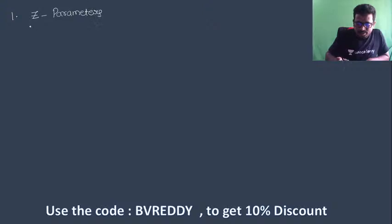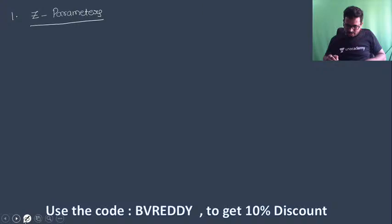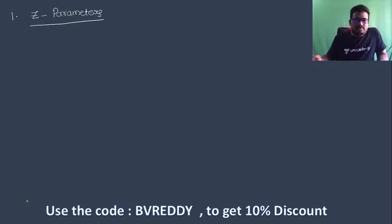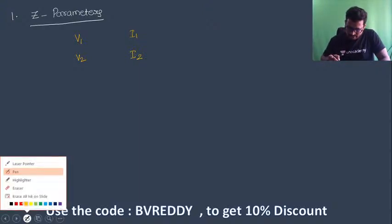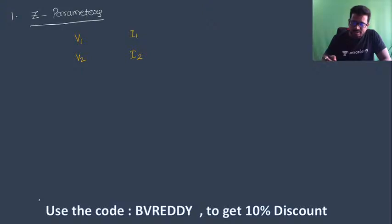Z parameters. The first parameters we are calling as Z parameters. In case of Z parameters, we have V1, V2, I1, I2. These are the four variables we have. Among these four variables, as I told, at a time we'll take two as dependent and two as independent. In case of Z parameters, I'm selecting these two as dependent and these two as independent.